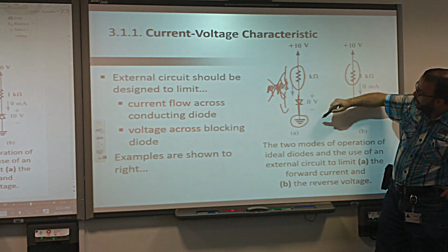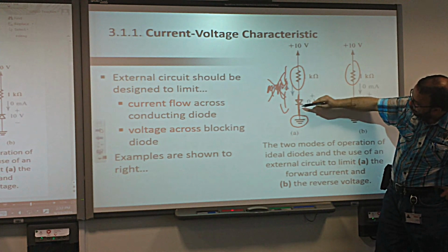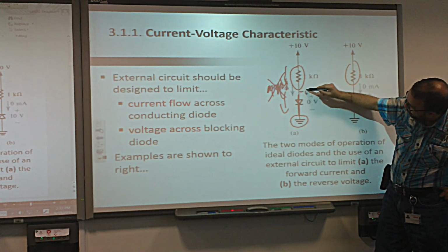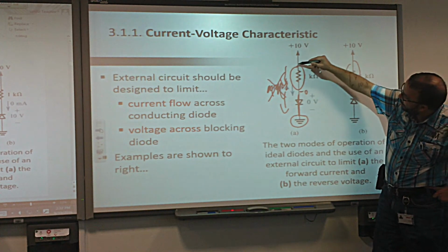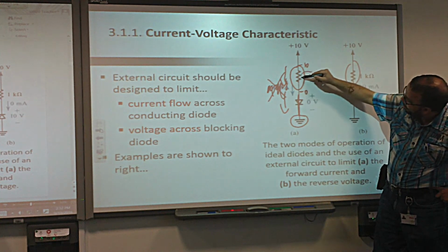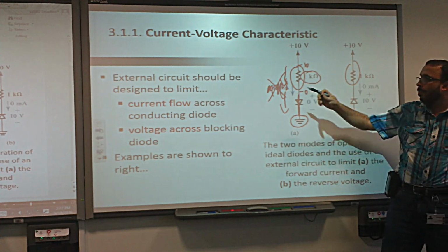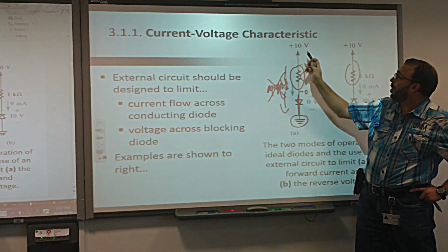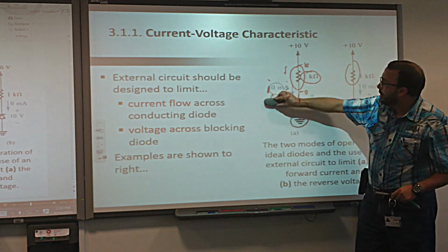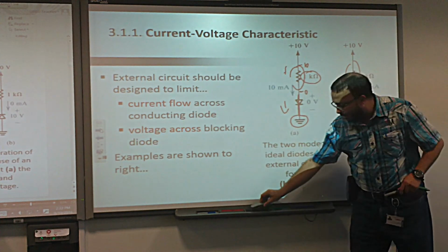So is the voltage here, there's no voltage drop here because there's no resistance. So is this voltage, what's this voltage? Is this 0? And this voltage is what? Is this voltage 10? So 10 minus 0 divided by 1K, 10 volt divided by 1K will be 10 milliamp. Okay, good. See? That's why now we have this.